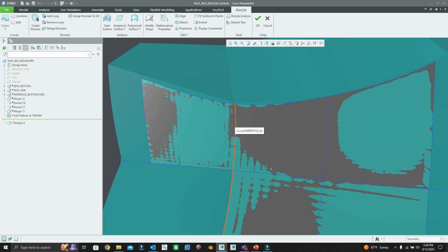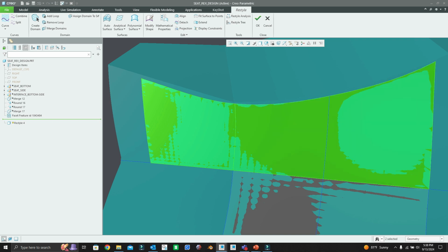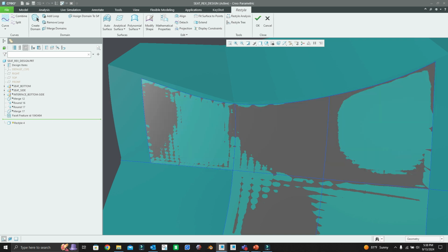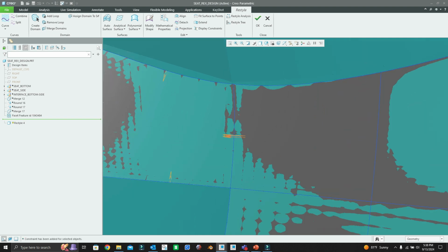And now let's adjust the continuity between this surface on the left and the surface on the right. So to do that, we first have to display the constraints, select a surface and middle click, and we get these arrows. If I select an arrow and right click, it'll tell us the continuity. So currently it's at tangent, but I can adjust it to curvature. And when I do that, you see that we get these two arrows aligned closely to each other there.